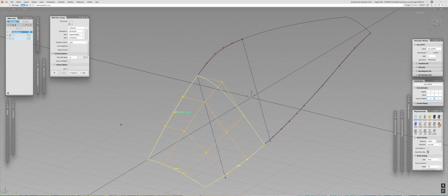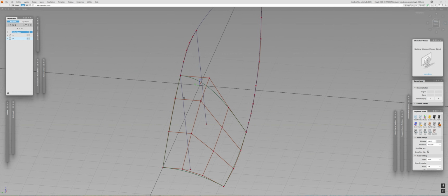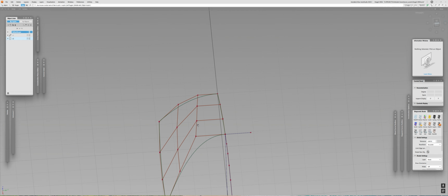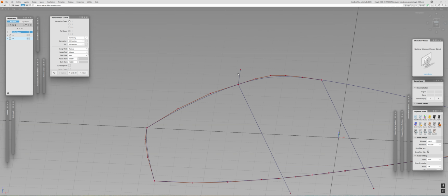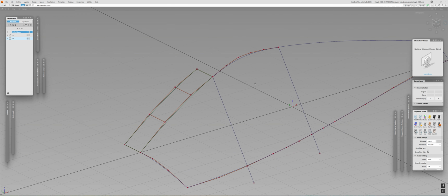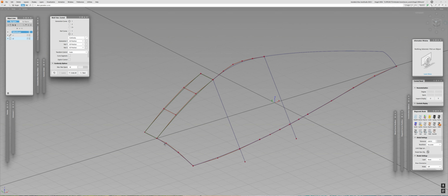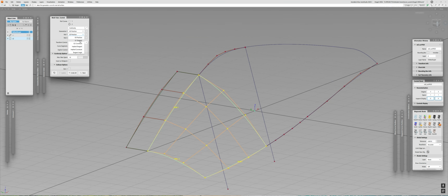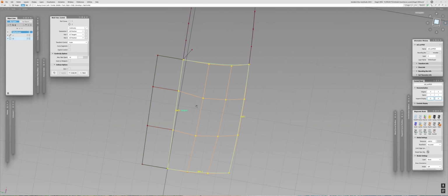So instead of using implied tangent, we can work with a different approach, and this is a separate additional guiding curve which you use to create a guide surface. Right now, for example, I will use the one generation curve and one rail to create this guide surface for me. Actually, I need to undo it and quickly create it again. So first, this one, and this one. Now for the rail one, I can switch it strictly to tangency, and that's better. Now we have the proper direction.